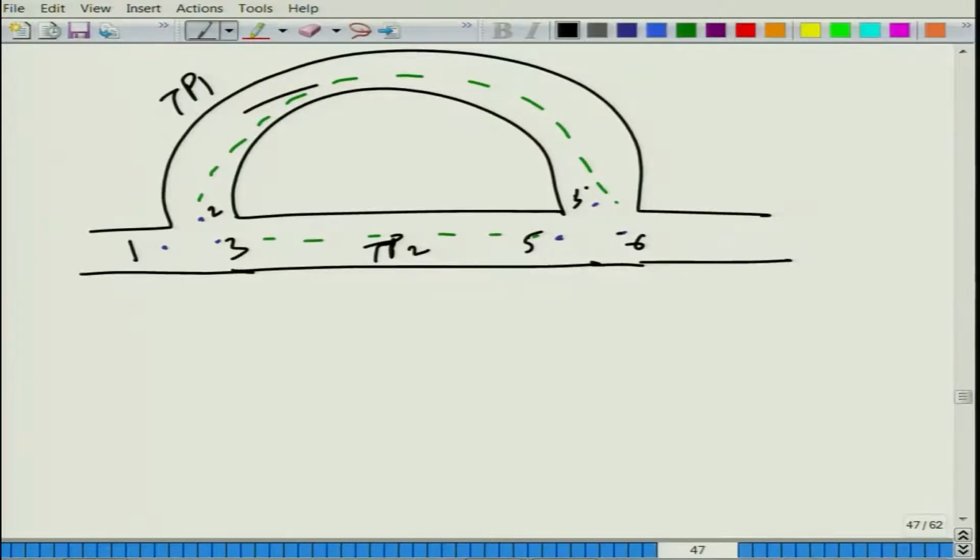So, what we will do is equate the pressures at this point 1, 2, 3 where they have come together at a very small point: P1, P2, P3 tilde, they are all the same. So, these are junction laws. Junctions are really points where 2 or more elements are connected together. Those elements themselves can be a 2 port element or a multi port element, depending on the network involved. But for analyzing such a system, what we will do now is write down the junction laws.